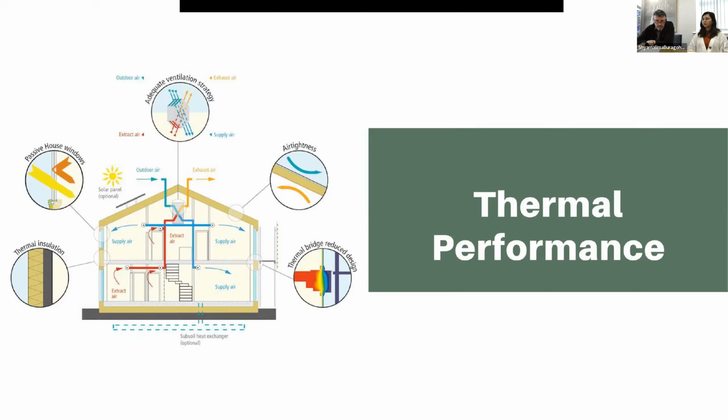The building geometry and the building orientation are very important items as well, and they can be the cheapest of all options to improve the thermal performance of a building, simply by turning the orientation away from the warm areas in hot climates, and towards the warm areas in cooler climates, having your useful solar gains where you want them, and blocking out solar losses.